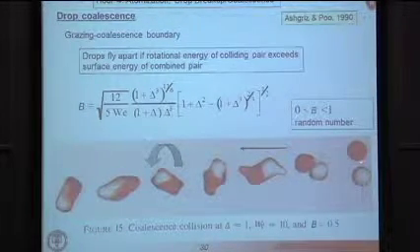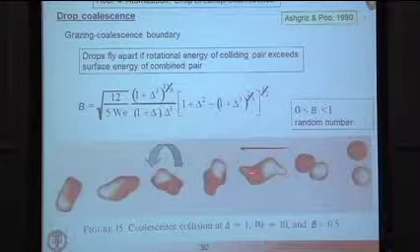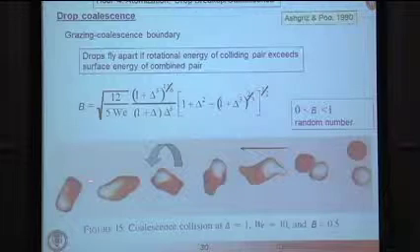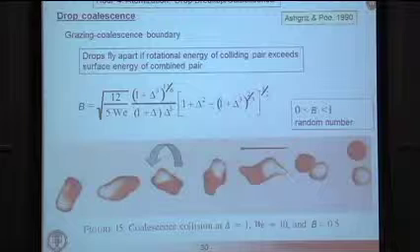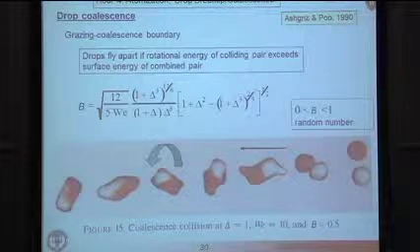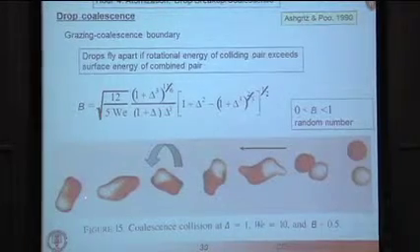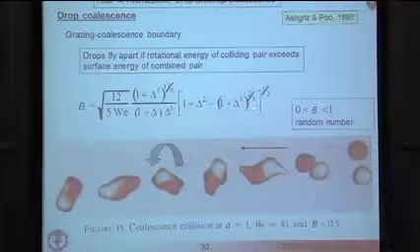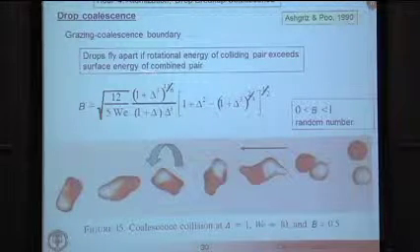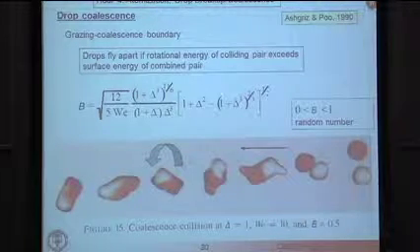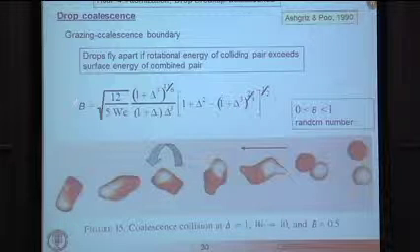And you can see here that basically these drops are going to coalesce. Notice how they're kind of rotating. The red goes to the bottom and then comes back up to the top again. If the energy associated with the rotation is enough to overcome surface tension, these will fly apart again. But in this case, they coalesce. And there's a theory that describes whether this rotational energy exceeds the surface energy, and it leads basically to this result, where we have the size ratio of the droplets, the Weber number, and the impact parameter.